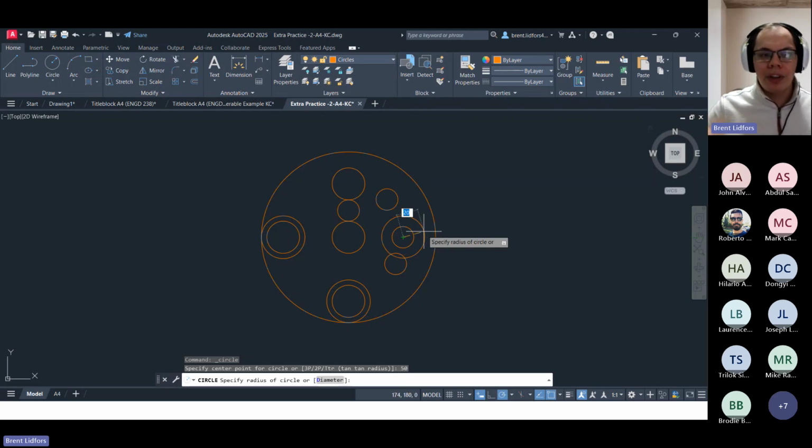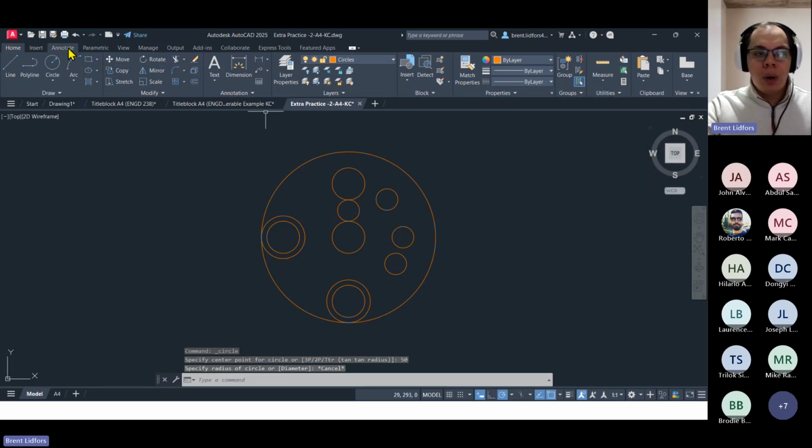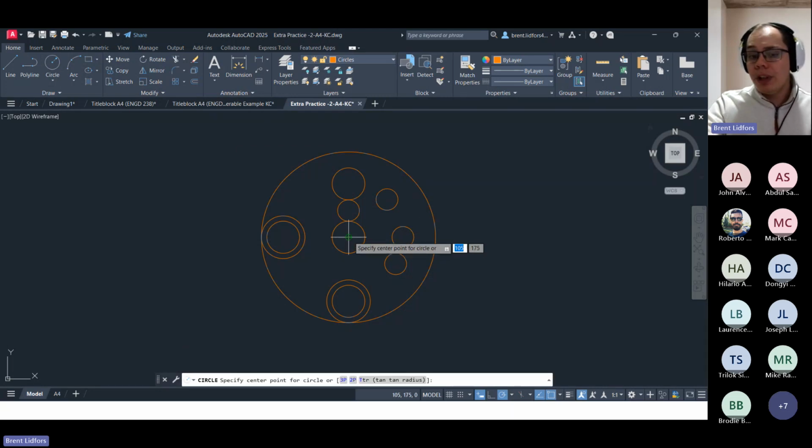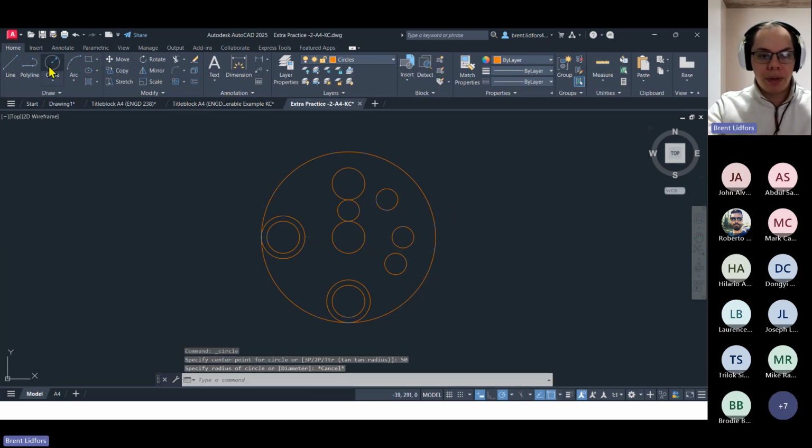There were a couple of cases where the distance was just very slightly out. What I figure happened was maybe you did use object snap tracking, but when you had this tracking line, you didn't exactly type in the numbers. Remember, I just have to hover over that object snap, and then as long as I have the tracking line visible, I can just type in the radius that I need across that tracking line. So typing in 50, I think I accidentally grabbed the quadrant there.